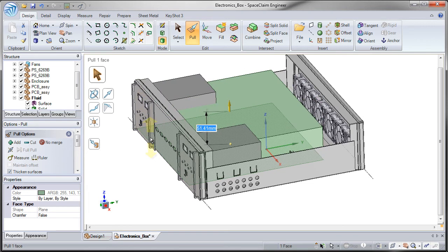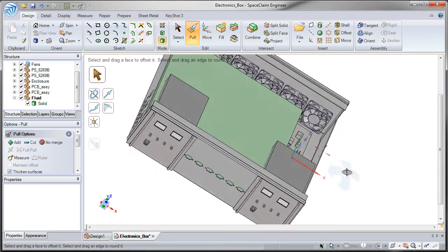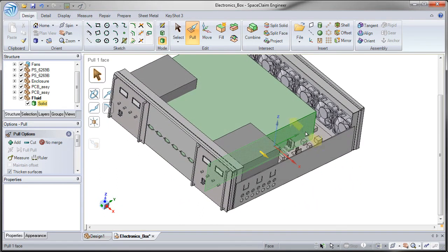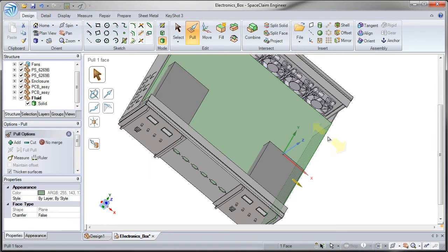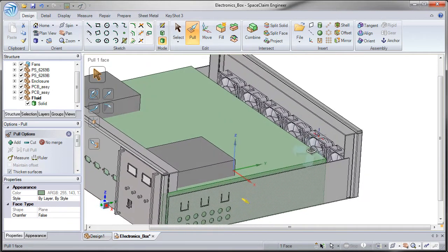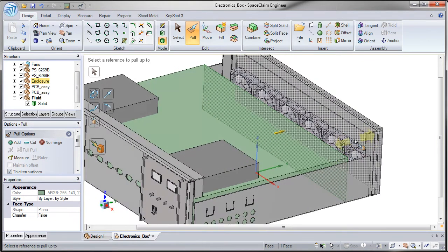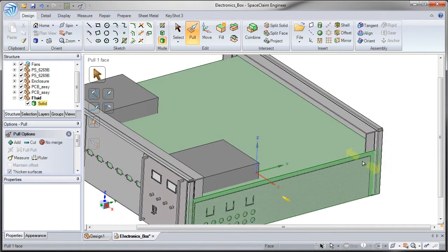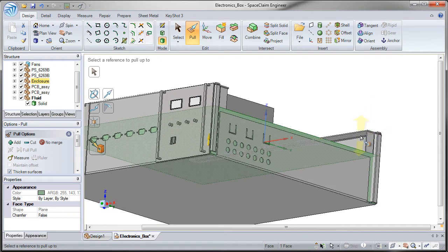Now what I want to show you is this. I have the walls that are marking the inside of this body, where it should be. So I can take one face and go up to this wall. Even though I didn't sketch it to be exactly in that location, I can still easily take one face. Notice up to is also in our mini toolbar, up to the back face, so you can make sure that it's going to fit nicely into the model. Even grabbing the top and going up to the top of the box that we want.